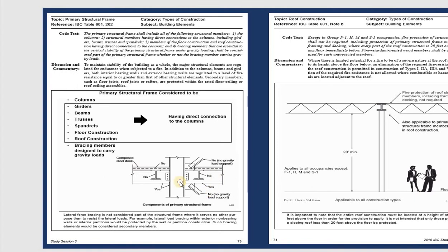That's one material for the ceiling, and one for the wall. Especially on the wall, they specify right here that they need to show the fire rated material. That's the specific material. You can use the chipboard right here, 5/8 Type X, to make sure it qualifies for the fire rating. The other ones say no, that means they don't need a design or special material for fire.